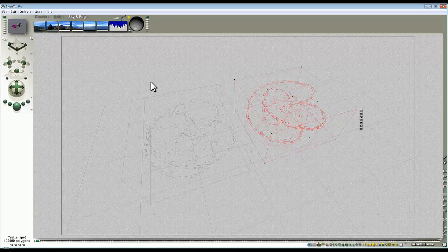The new ones use parametric mapping, which relies on UV maps. Hence the use of UVmapper to provide some UV maps. If you wanted to change the kind of UV maps that apply to these models, you can do that by exporting the model, putting it through UVmapper and then importing it back in. Be a bit careful with exporting models from Bryce because Bryce can crash, so make sure you do it in a new scene. I'll show you, that's the easiest way.